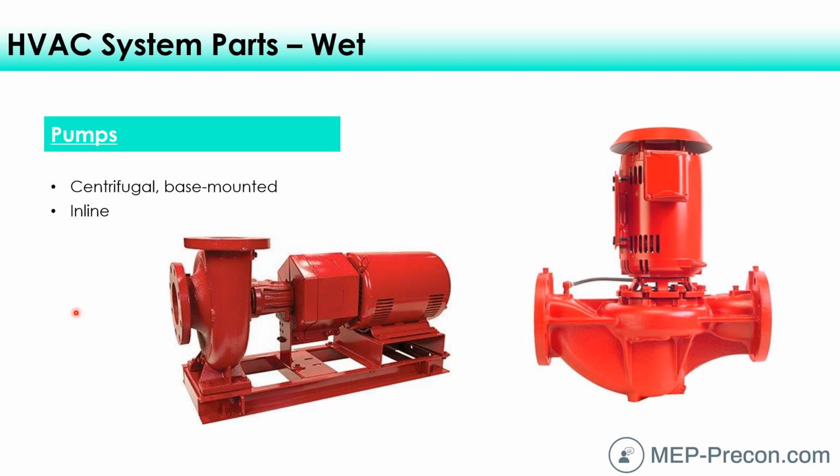Or a centrifugal anything? Yes, it comes in here and it gets discharged 90 degrees from how it comes in. So there's just a propeller in here, basically within this volute, this casing of it here, and it generates a lot of pressure and it discharges the fluid through the piping, 90 degrees from how it comes in. An inline pump is generally for a little bit smaller pumps, a little bit easier to install, maybe takes up a little bit less room, less fittings and so forth, and so you could put it straight in line, just like the name implies, within your piping.